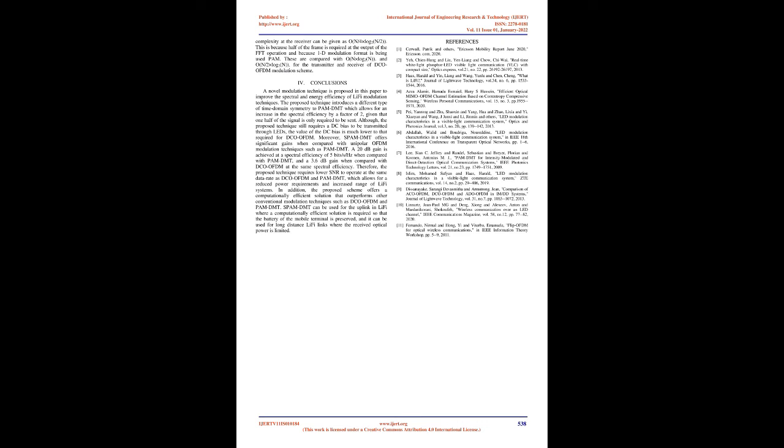3. Numerical results. A numerical study was conducted to examine the performance of the proposed modulation techniques compared with DCO-OFDM and PAM-DMT at the same spectral efficiency. The comparison is based on an additive white Gaussian noise, AWGN, channel with zero level and upper clipping to model an ideal optical front-end design of a LiFi channel. A LPF is assumed to model the frequency profile of the LED, similar to many studies.